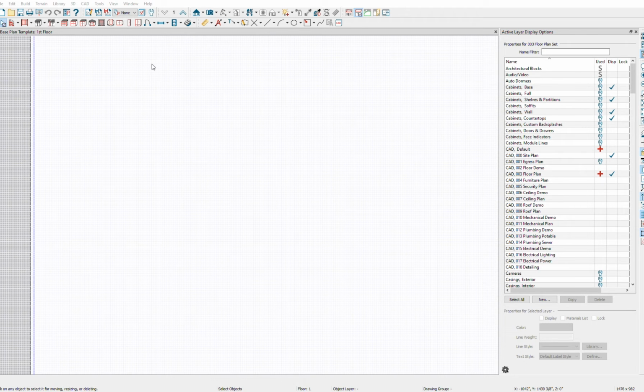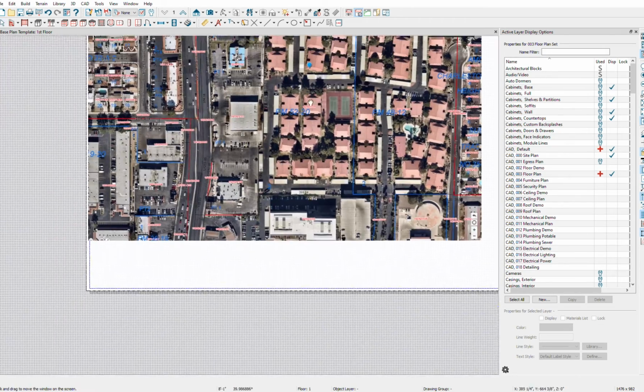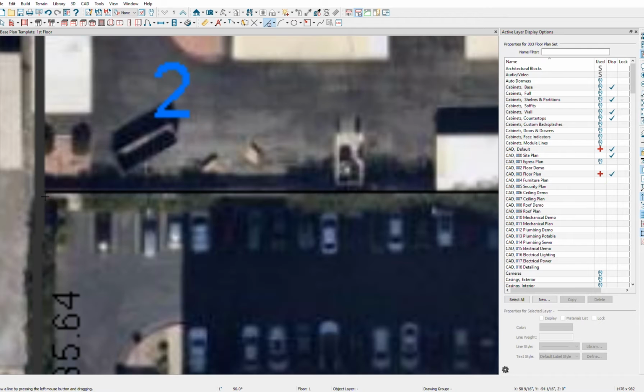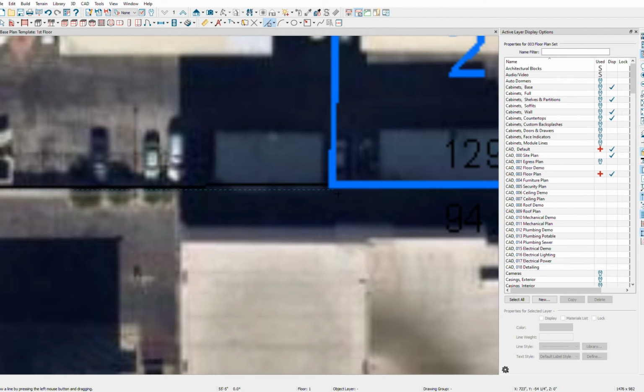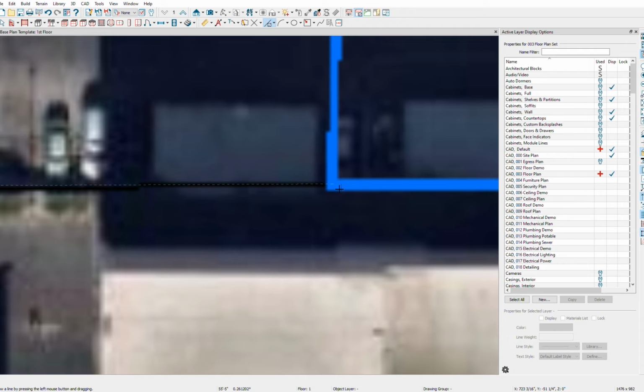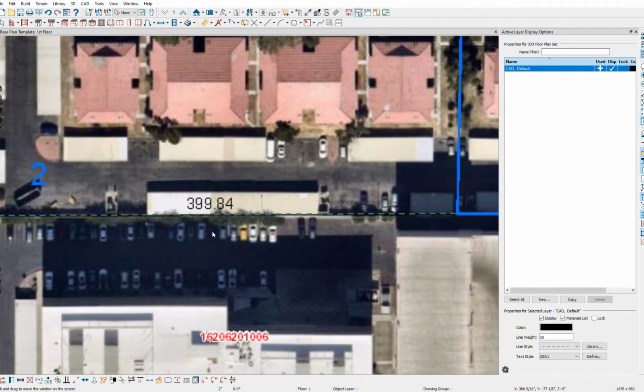After importing the image into Chief Architect, we need to scale it to the correct size. I keep the Assessor's map layers on and the image so that I can scale the image using the parcel dimensions. I start by tracing the line of the largest dimension I can find. Then I compare the size of the line I drew to the line of the aerial image.